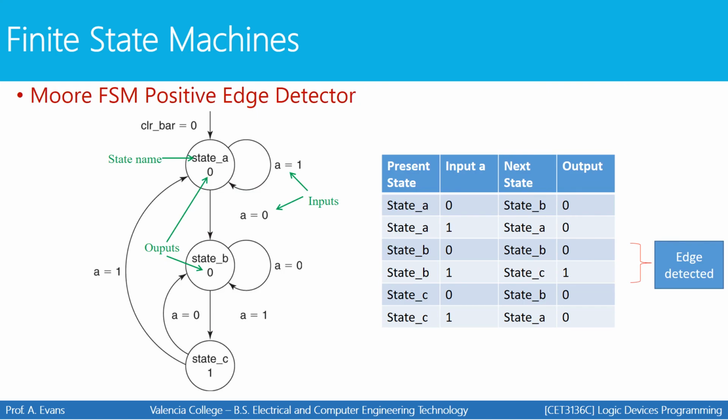So, when you begin designing a state machine, you have to start with a diagram. You have to have a roadmap, a clear path for what's supposed to happen. You need to define all possible states. You need to define how you move from one state to the next based on your input. Do not start writing code without a roadmap. You need a diagram. You need to know how you're going to get to where you're going.